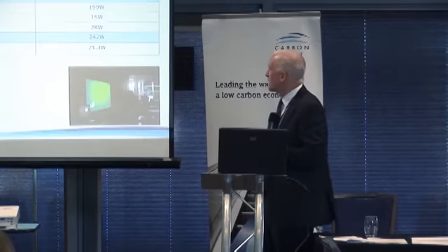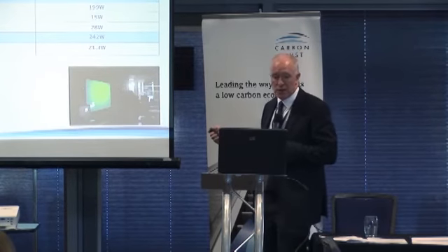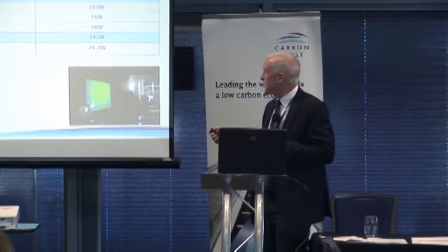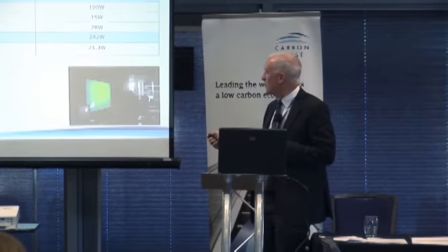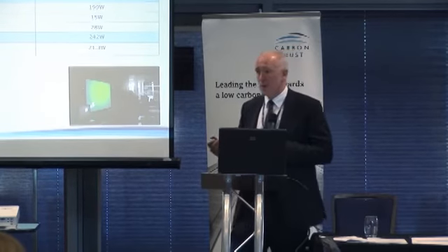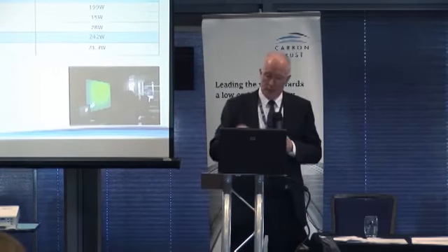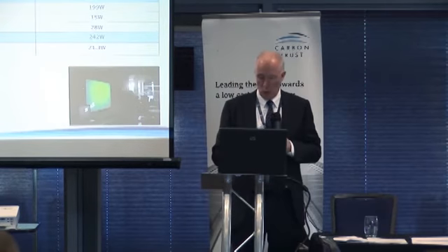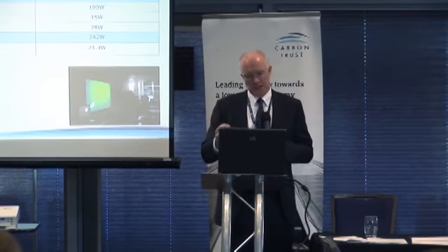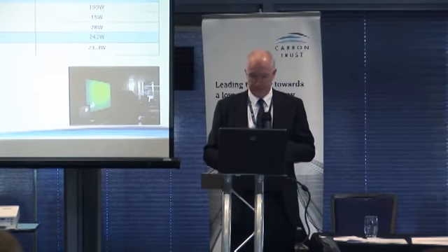That's the reality. But your projector here, this is some detailed monitoring. Projector nearly 200 watts. The whiteboard and speakers taking about 15 watts. The laptop plugged into that 28 watts gives you nearly a quarter of a kilowatt, 242 watts. And shut down in standby mode at night, unplugging the laptop, but all the rest in standby mode, 21.3 watts. So even in standby mode, the standby projector with the little light on and the speakers powered up, and the board takes a small amount of energy there. So again, some detailed monitoring sends out some messages there.